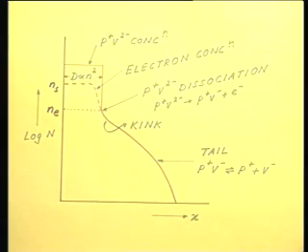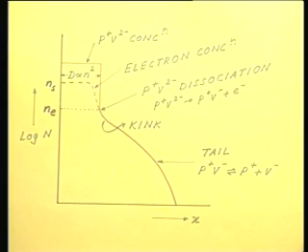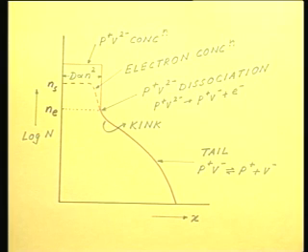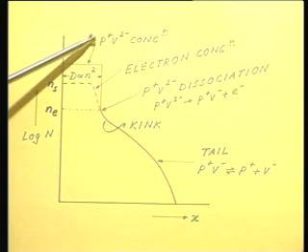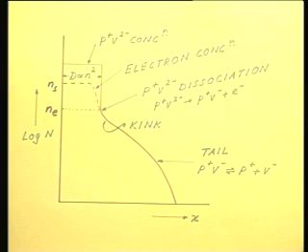Now, in this flat topped portion, you see D is proportional to n square, that is, this is the region where the phosphorus impurity has interacted with the doubly negatively charged vacancies. And that is given by this, P plus V2 minus.